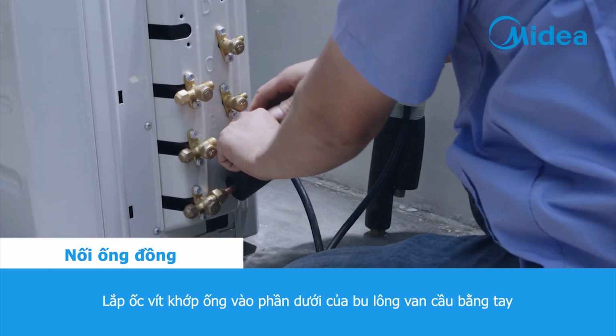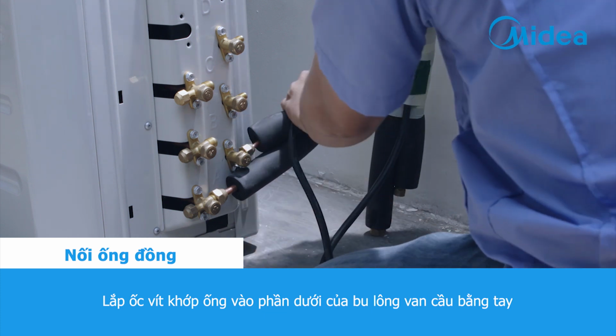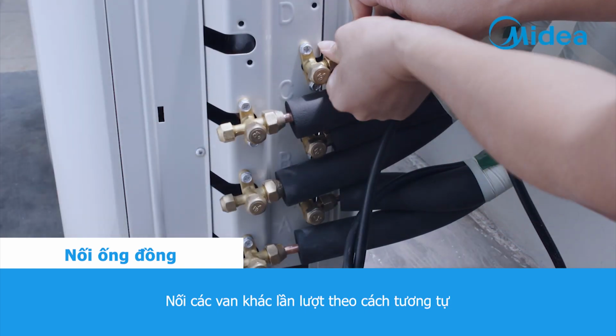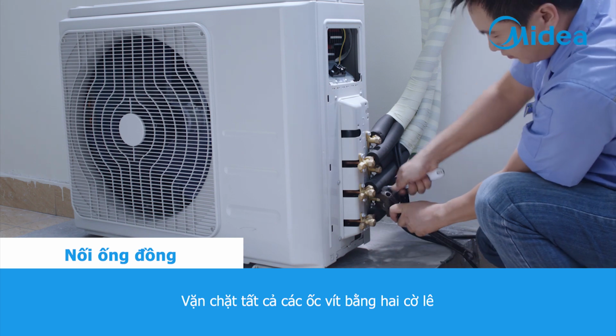Screw pipe socket nut to the bottom of globe valve bolt with hand. Connect other valves in turn like this. Fasten all the fixing nuts with 2 spanners.